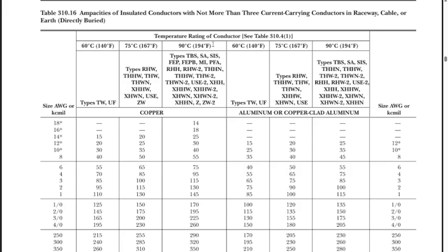All right, there's 3 types of temperature ratings. Usually we go with the Celsius, even though in America we do Fahrenheit for everything. But for the insulation types, I think it's just because it's easier numbers to remember. I think somebody just kicked this off and no one ever changed it. But we go with 60, 75, and 90. And also the code sections will reference the Celsius.